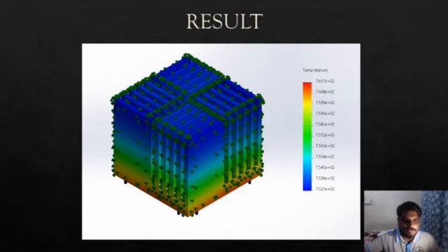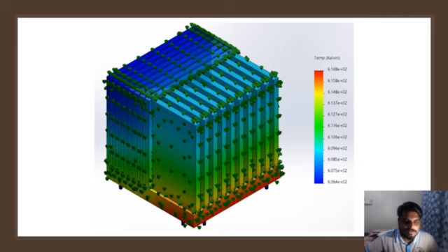Now we see the result for the temperature data for design 1. This is a heat sink made out of aluminum alloy. It's a conventional heat sink, but parallel to the opposite side. The maximum temperature is 7.617 E plus 2 Kelvin, that is around 488.5 degrees Celsius, and the minimum temperature is 7.527 E plus 2 Kelvin, that is around 479.5 degrees Celsius.